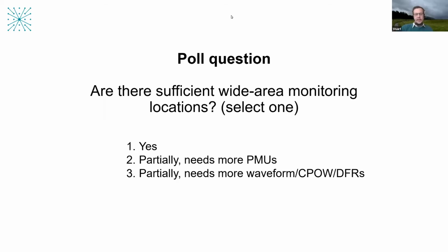Yes, I think PMU data, particularly from the system operation point of view, if you're sitting in a grid control room, PMU data is the big thing that you're interested in to help run the grid in real time and to analyze, essentially to be the next evolution from the EMS world. So EMS is SCADA, it's only giving you magnitudes every 1 or 2 seconds, and they're unsynchronized. PMU is giving you phasor measurements, magnitude and angle, and they're synchronized. They're what you're really trying to get to with a state estimator to feed into your stability studies to know the real state of your system.